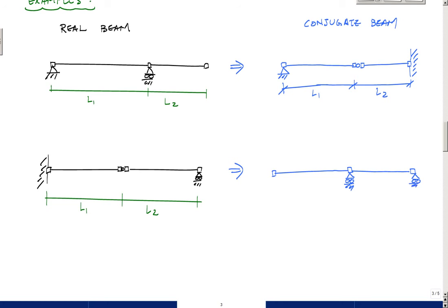And this looks unstable, right, if I have a horizontal load, but anyway, it'll work in terms of the conjugate beam, as long as the loading is vertical. But this is technically an unstable structure. But again, this is how it gets interpreted in the conjugate beam, and all you've got to do is use statics with the curvature as a loading to solve for the deflections.